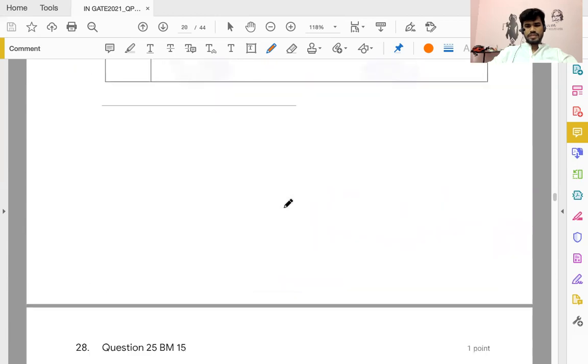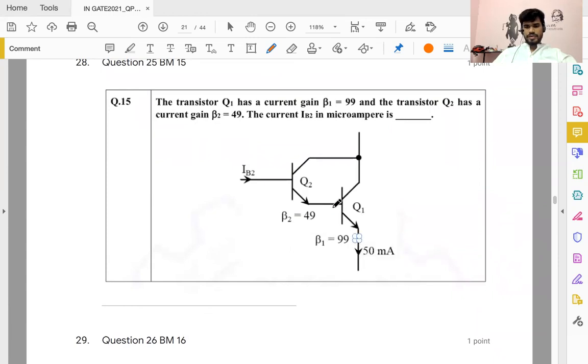could be easily analyzed. Okay, we have emitter, base. Then emitter, base. This emitter current is given. This is IE1. All you have to remember is one relationship, the relation between base current and emitter current. Base current is very, very small. So this is the base here. That base current IB1, base of the first transistor, is going to be very, very small. So given emitter current, you multiply that by,